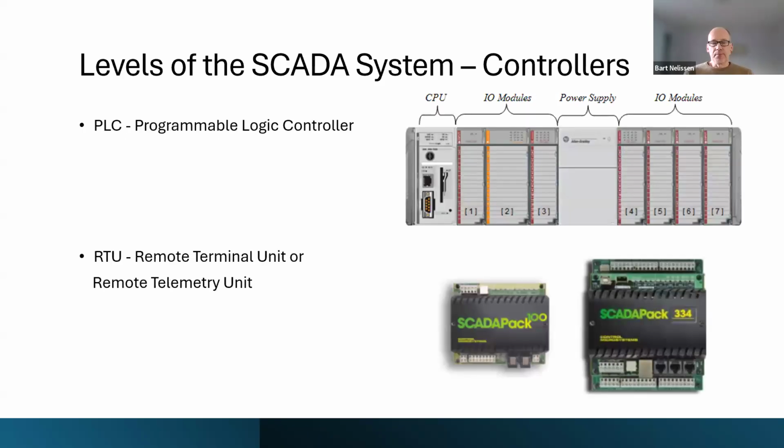So what that looks like in PLCs or controllers is something like this. A PLC, which I think stands for Programmable Logic Controller, is a device that gets wired physically to all the devices, your instruments out on your plant floor, your sensors, etc. And it is capable of monitoring the inputs, analog and discrete, and it is capable of controlling the outputs, also analog or discrete. And it's got three main components in a PLC in order to do that.